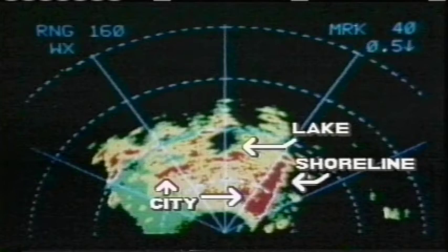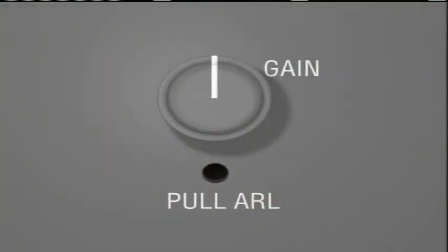Because the intensity of ground returns varies widely due to the changing angles that the radar's beam is illuminating objects on the ground, the flight crew may use the manual gain control to obtain an interpretable ground mapping display. A good rule of thumb is to fine-tune a map display by varying both the gain and antenna tilt controls until the presentation is optimized. The gain control knob is active in ground map mode for both radars.